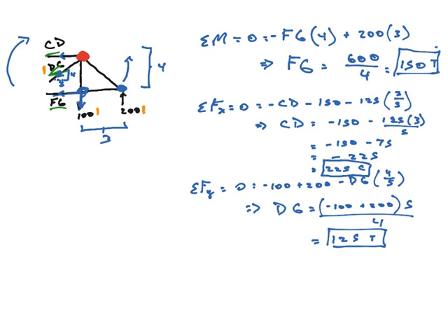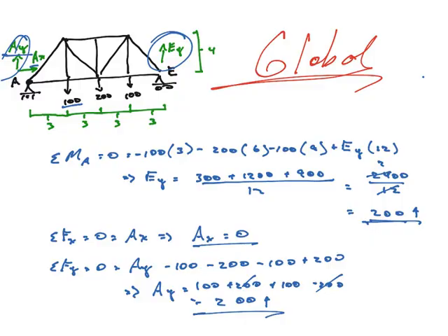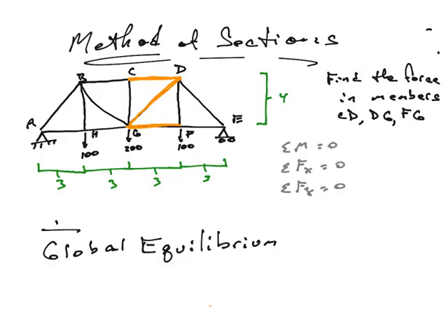All right, so this is method of sections. This is the theory of it. And it's just a secondary technique. If you don't care about the full truss, you only care about particular members. So in this case, we only wanted these three. If you have the ability to cut your truss into two separate pieces by cutting along those members that you want, then method of sections is the best way to handle it. If not, then you're probably using method of joints. And you're just going to have to take the time to find a bunch of members, even if you don't really care about them.